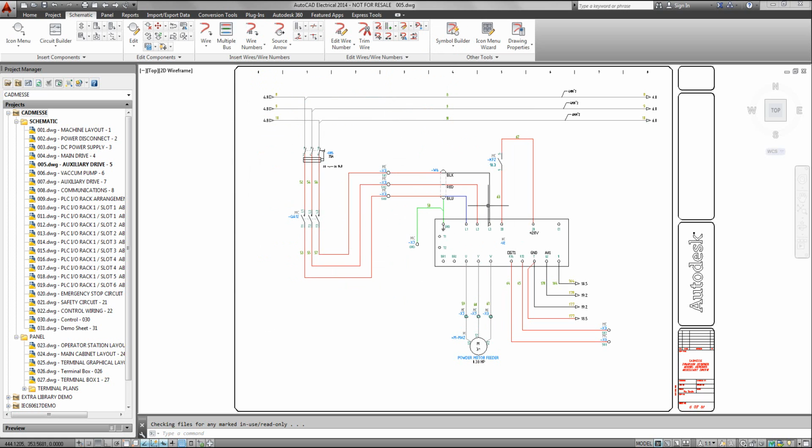The next part is our workspace. AutoCAD Electrical always works within the model space. So when we drop in or create a new drawing, our drawing border is always placed in. Now I know this is in a white background. This is basically so it's easy to see on the video. Normally a model space is black and the layout space is white, but like I said, for AutoCAD Electrical, we always use the model space.